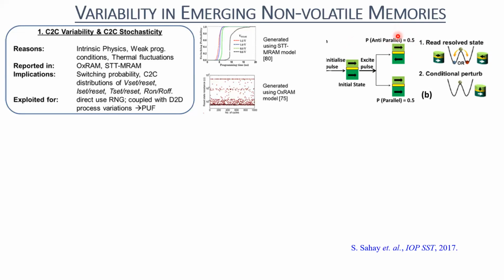Now, if electrons are flowing, like charge current is flowing through this, what that means is electrons are flowing through this layer. When electrons flow through this layer, in the ferromagnetic layer, you have a property which is called spin transfer torque. So what exactly happens is, the spin of those electrons which are coming into this layer is randomly distributed, and the magnetic moment of the electrons in this layer is fixed in this direction.